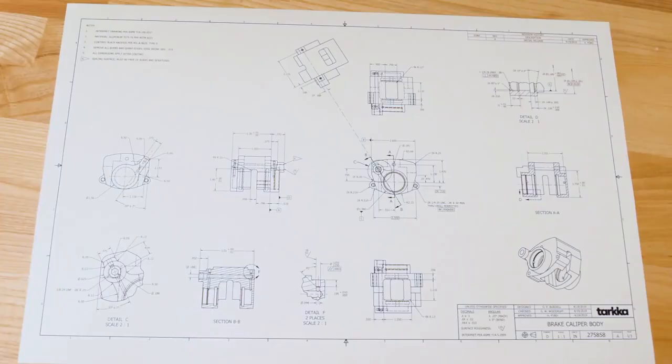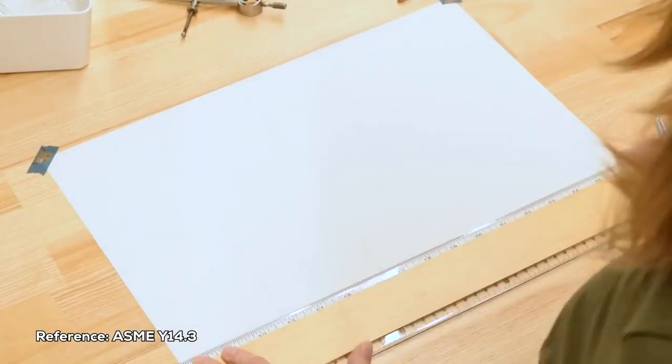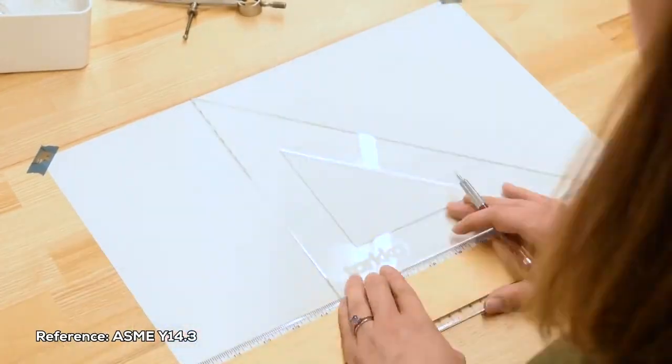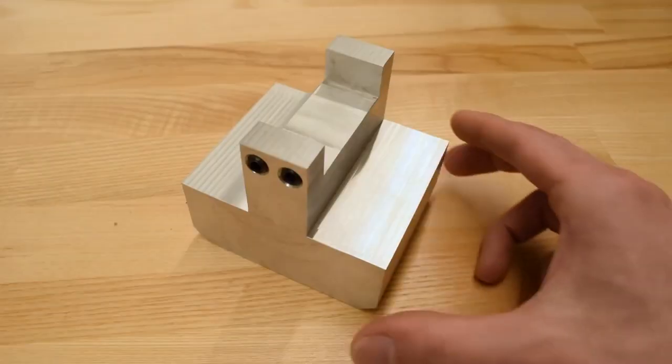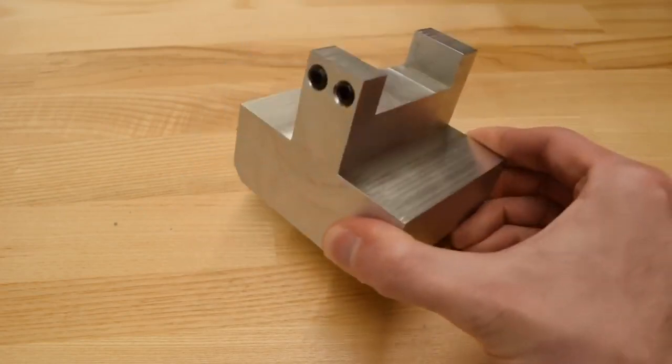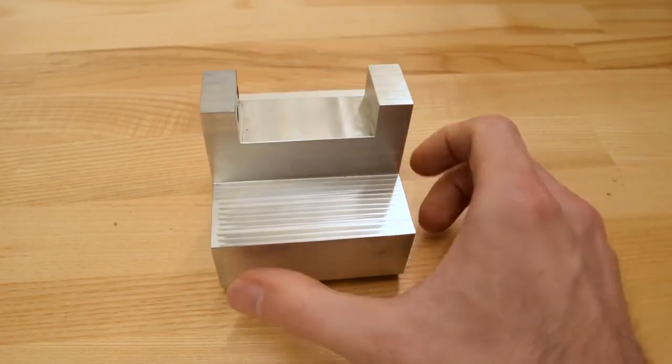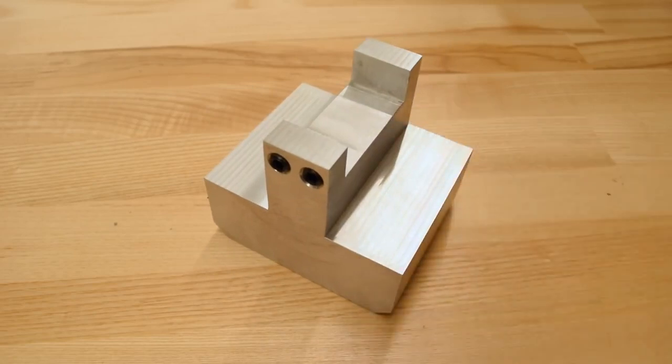The face of the drawing will usually have 2 or more views, and they must have a particular alignment to each other. We're going to switch to hand drafting for a second to talk about where this convention comes from. To draw this example part, we're going to choose a view to be our primary or front view. But there are other features of the part, like the larger tapped holes in the slot, that can't be seen, so we need to create additional views around the front view that show them.